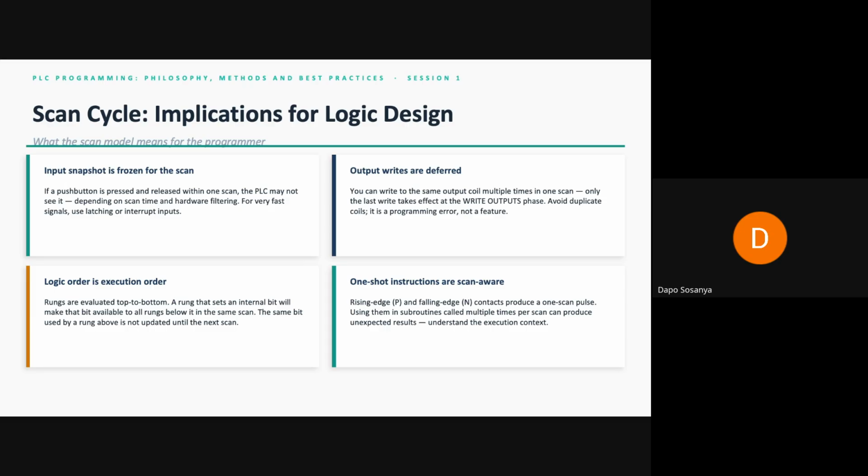If you use them in multiple subroutines, they might change at any time, right? You have tied this rising edge to a particular tag, and you are using that tag in multiple locations. After using it in subroutine 1, subroutine 2, probably you are still going to use it in subroutines 3, 4, 5. If it now changes, you get an unexpected result, and that is not determinism.